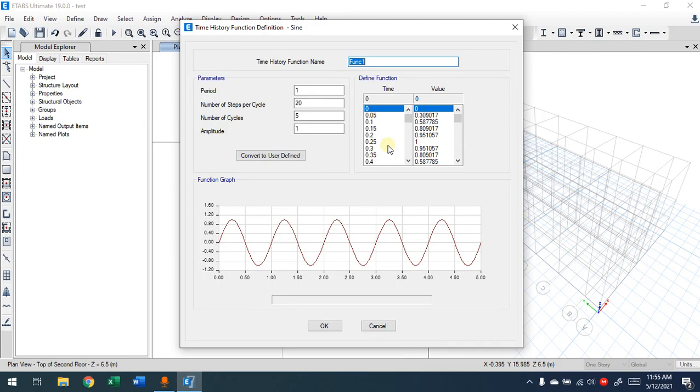There is an international one that records basically seismic data, which you can bring here and add to the load cases. In this case, you're going to use a real analysis of an event that happened. For example, you are designing for a seismic case that happened in Cyprus, so you can get the data and bring it here.